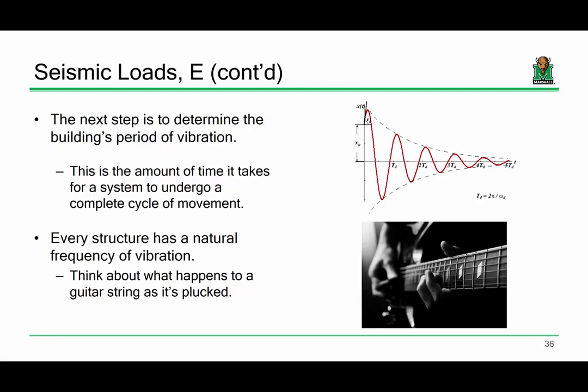And one of the fundamental rules of structural dynamics is that under free vibration, all structures vibrate at their own natural frequency. It's why whether or not you play a string very softly or you wail on it, you still get the same note because it's still vibrating at the same frequency. Okay? And so natural frequency, if you ever take a course in vibrations or structural dynamics, natural frequency is the day one lecture. It's the first thing that you are tasked with determining.